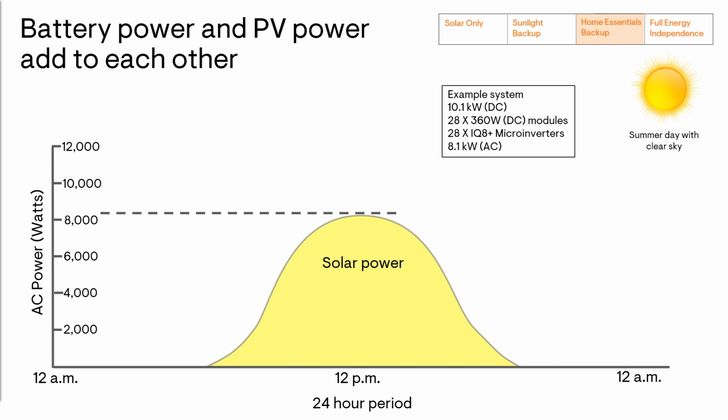The option to add a small battery to a large solar system is pretty unique. Typically, manufacturers limit the power of the solar system to be about 50% higher than the battery to ensure that the solar system itself doesn't cause a collapse of the microgrid by attempting to feed more power into that battery than it can handle. In other words, if a customer had a big solar system, then they would have to get a big battery to match it. Homeowners sometimes feel like they're forced into buying a much larger battery than they really need.